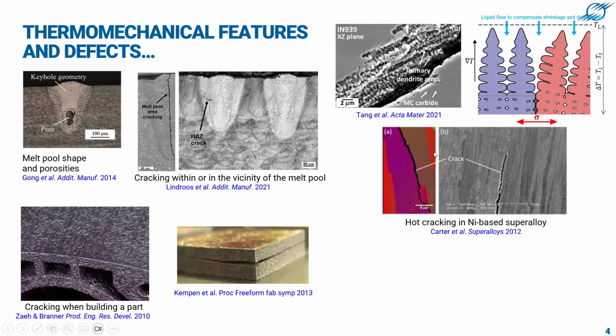And this is a defect, since at that time the mushy zone is not permeable enough for the liquid to heal the crack, and so the crack remains.